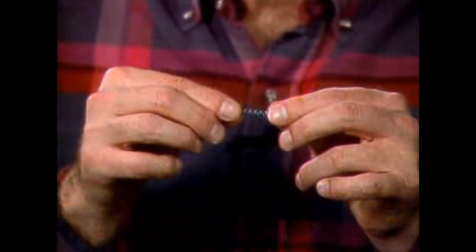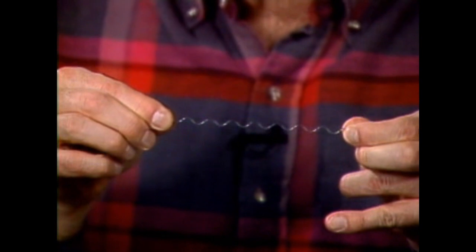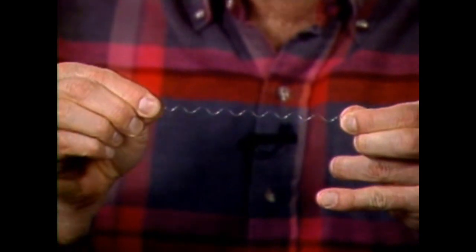Solids that are highly elastic will generally yield to the deforming forces of stress. Steel, for example, can withstand a lot of stress before it loses its elastic properties. That is, before it reaches its elastic limit. The elastic limit is the point at which the force applied to a solid exceeds the ability of the solid to return to its original shape. It's the point at which the solid will remain deformed.